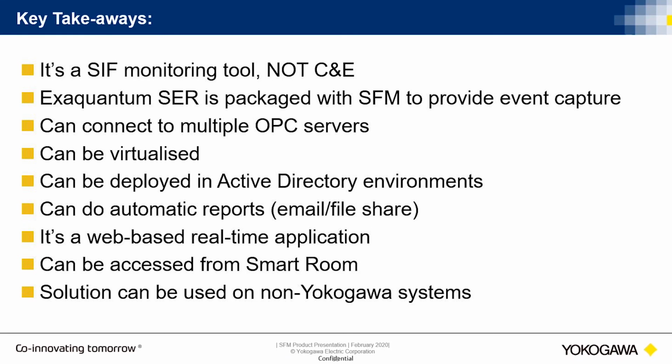And web-based real-time application. It means that if you know what you're doing, you can put the port number of that website onto your plant firewall and make that web page accessible through the offices. So you can access the SFM pages from the smart room, for instance. And I have clients who sit in their corporate offices and get SFM pages all the way from a platform in the middle of North Sea.